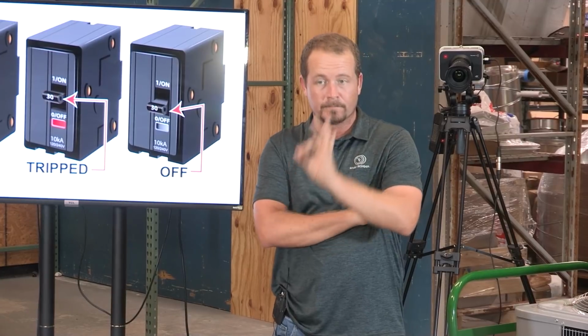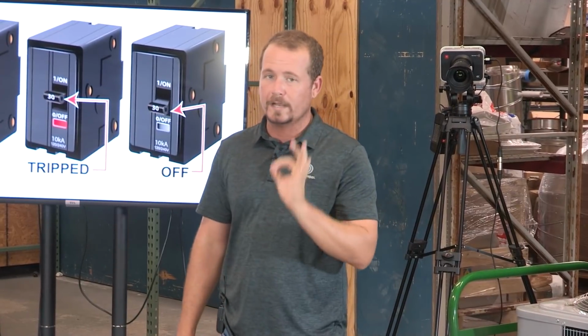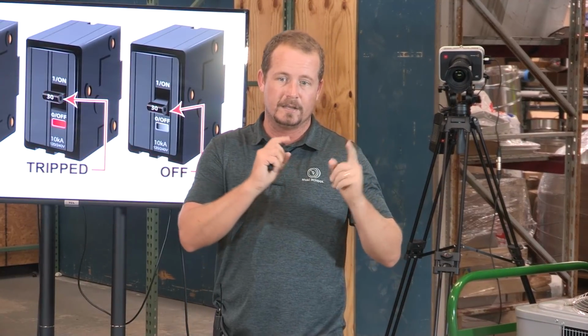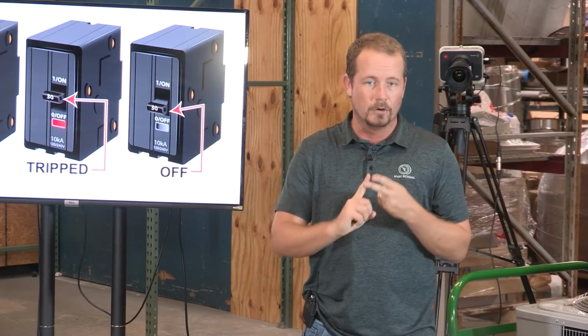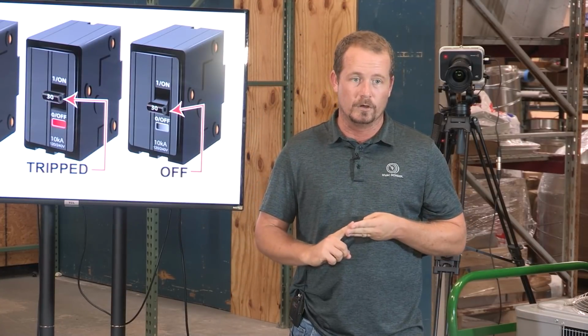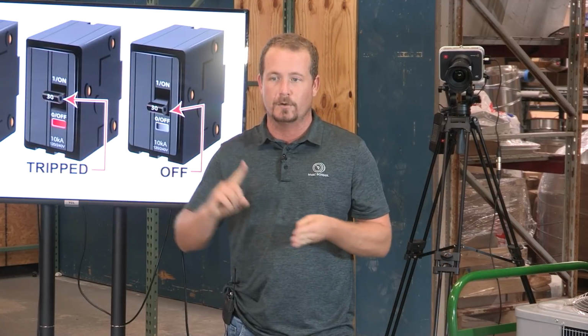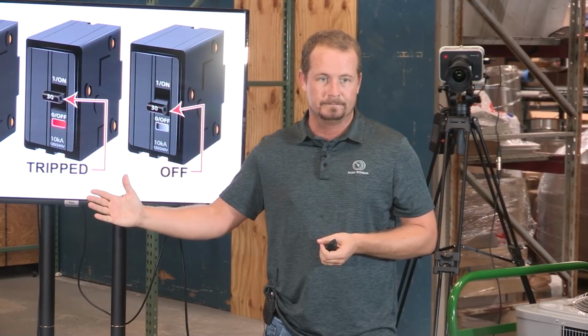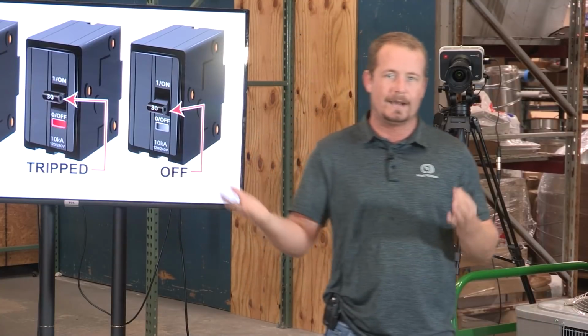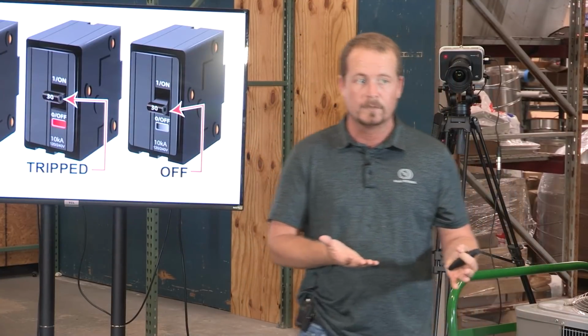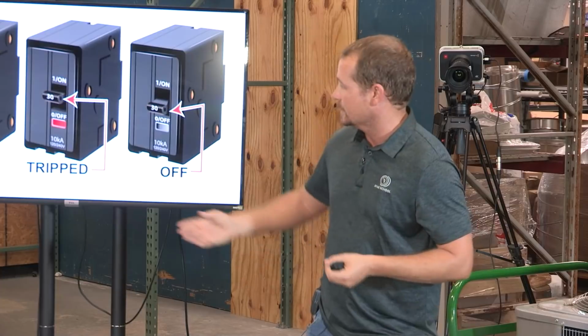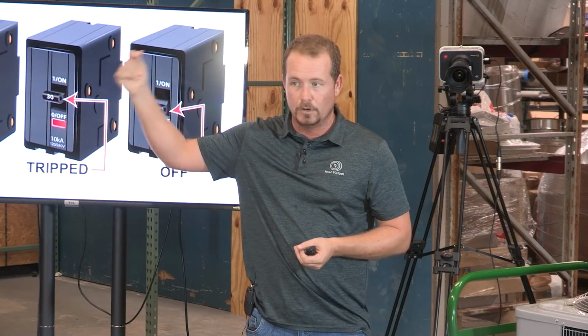No, it's not. And so we have to make a quick distinction between things that trip breakers, blow fuses, go out on overload instantaneously, and things that trip breakers, blow fuses, go out on overload over time. Because those are two very different categories of problem, generally. A short circuit is generally going to cause this breaker to trip how fast? Right away. Boom, right away, right?